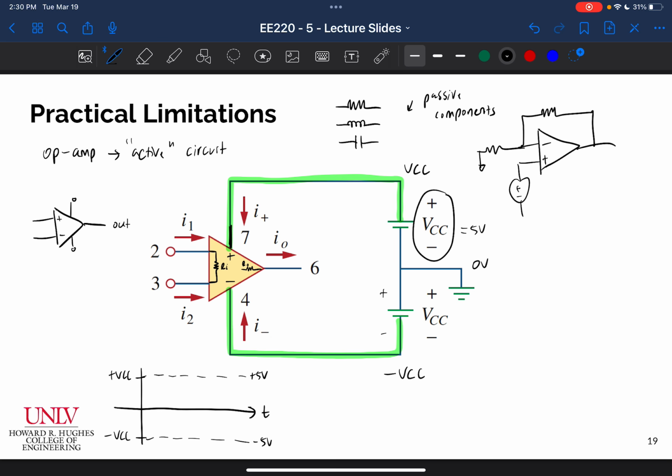I'm sitting here thinking, oh my gosh, so V out is equal to V in times 1 plus RF over R1. So if I just make RF over R1 huge, for example, let's say I make it 100K over 1K for this term right here, then I get V out is equal to V in times 101. And I'm like, oh my gosh, that's so exciting. So if I need to get a huge voltage at my output, this must be how they generate high voltage.